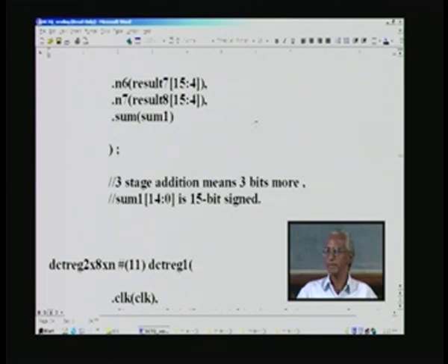After truncating this many bits, we always compute the PSNR, or what is called the image quality, and compare it with the corresponding MATLAB output. If it is quite close, say of the order of 0.5 dB, maybe a 2% accuracy roughly or less, then we truncate as per that. So that is how we do the truncation here, and here there is a 3-stage addition.